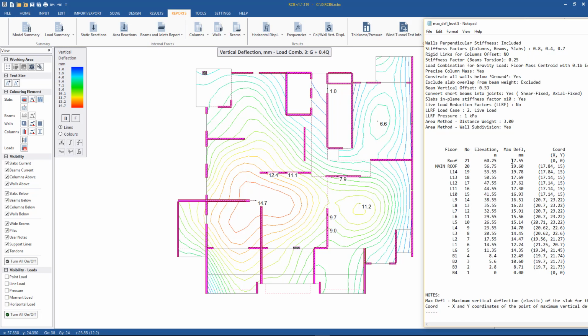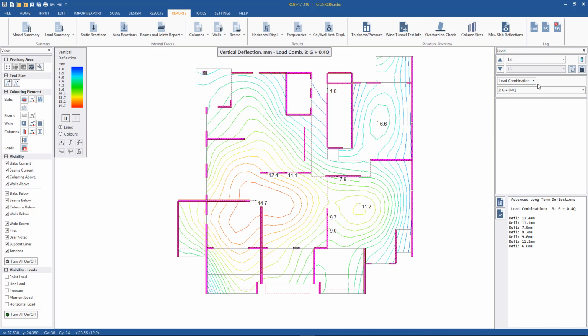And what I mean by relative displacement is that we get the deflections at the walls and we take that out. So basically what we're looking at here is displacement of the slab. If we were to go up to the level 14 roof, for example, we would see absolute values bigger than this 19 mil. So this is just showing the absolute values of the deflections on that particular floor, worst case. Not to be used for design, but just indicative, and it tells us whether or not we have forgotten to model a vertical element. So again, this is all done via Igross.